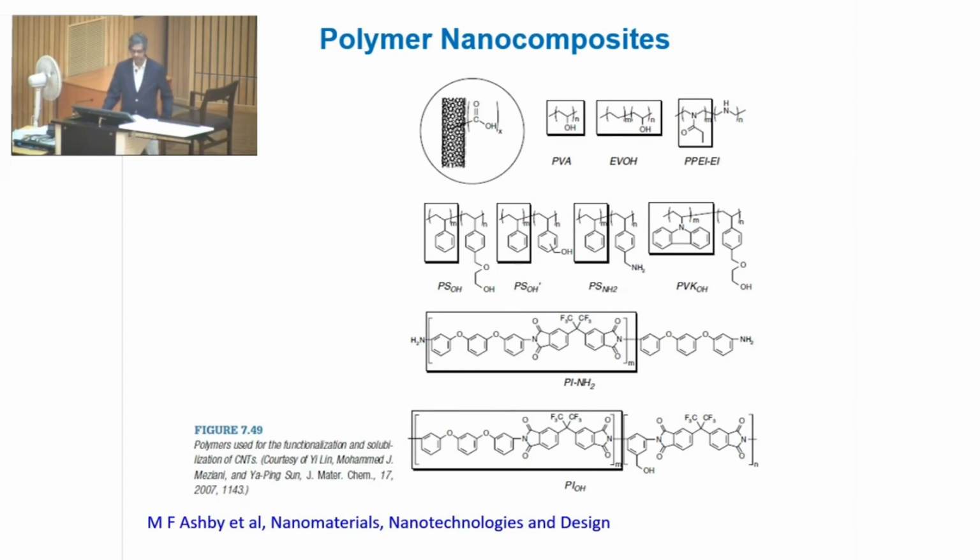Some solutions have been suggested in the literature to decrease this thermal resistance, and it is proposed to covalently bond the CNTs to the polymer to improve the phonon scattering. But it has also been suggested to use multiple CNTs instead of singular CNTs, because multiple CNTs can have smaller aspect ratios, therefore less interfacial area.